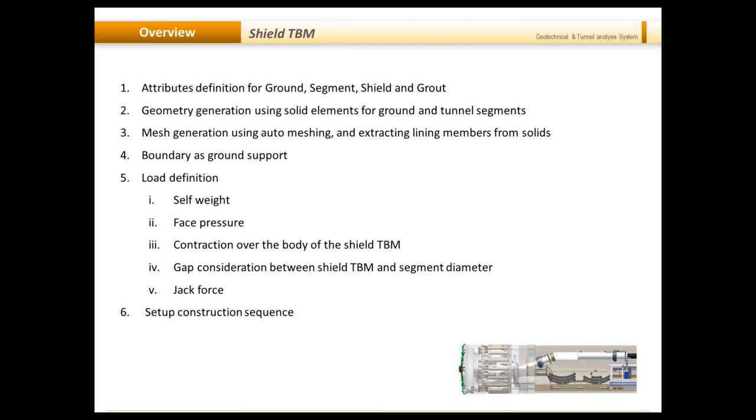Then we'll be setting up the construction sequence, and I'll use construction stage analysis control to define how the construction has to proceed. Then we'll be running the analysis. Actually, I'm running it right now in the background so that I can share the results directly with you, and then we'll be extracting the results.